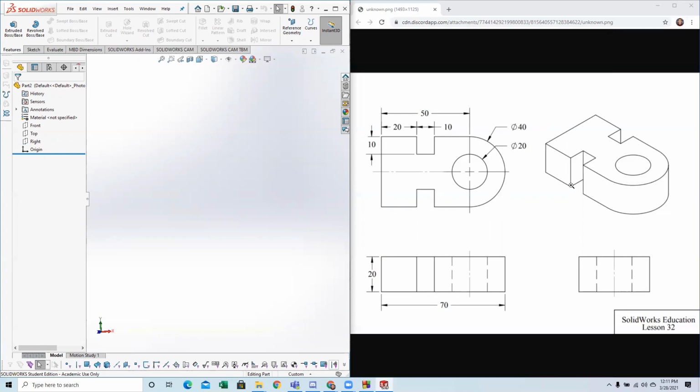So there's a couple different ways we could make a part like this. We could start by just creating the two-dimensional sketch shape and extruding it out. We could start by making an extrusion of the full part's contour right here and then cut through these little shapes right here. Or we could do a mix of those two, where we create a sketch of the outer shape and then we create a hole through the inside using an extruded cut.